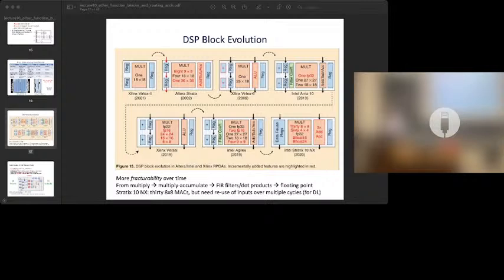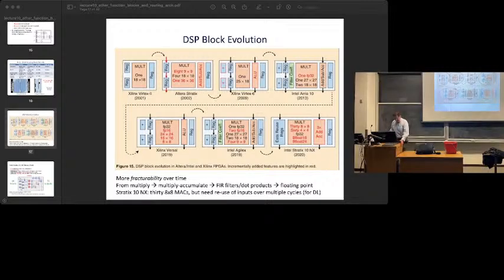So basically, more and more, Versal, Xilinx's most recent chip, has not only FP32, but also floating point 16, which is important for machine learning. So you can do things in reduced precision machine learning, so they put that in. And then you kind of see more and more precisions going in. So each of the vendors is kind of using these tricks of how do we recombine these multiplier arrays to make different combinations. And then this chip is a bit different.